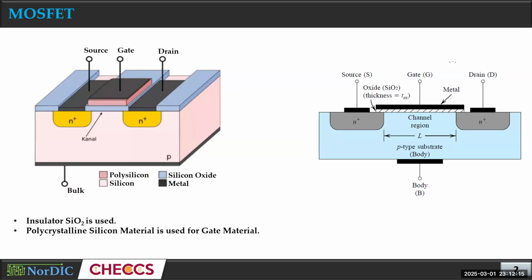Can any of you tell me, is the structure that is shown in this slide NMOS or PMOS? PMOS, and any other answers, or does everyone agree with him? P-type substrate, yeah. So is this PMOS or NMOS? The answer is NMOS. It's NMOS because you have to look at the source and drain, the yellow portions of the device. You can see that those are the source and drain, and these are N plus. That means these are N-type material. So if the source and drain are N type, it's NMOS.